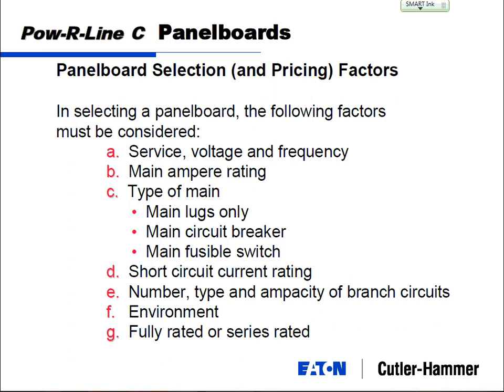NEMA 3R is the standard that makes it outdoor rainproof. Not waterproof, just rainproof. So that's kind of an important distinction. You can't take a hose and squirt it at the panel board, for example. Those are the three most common.